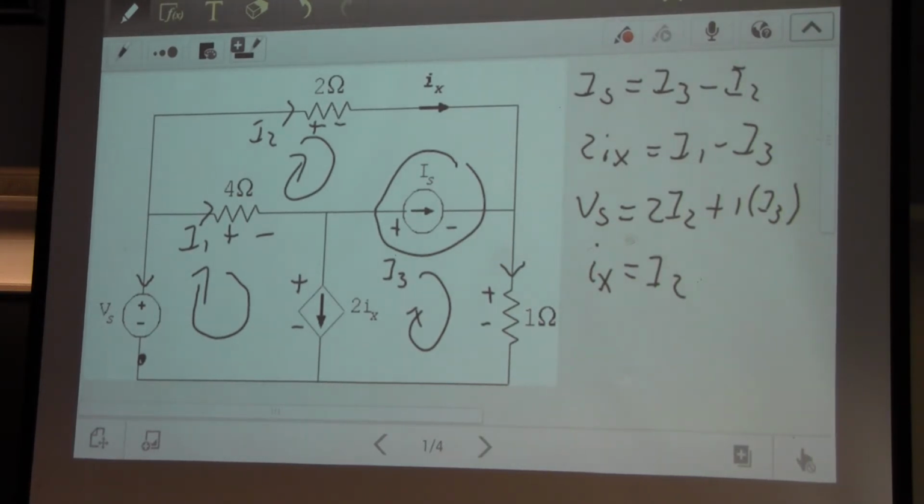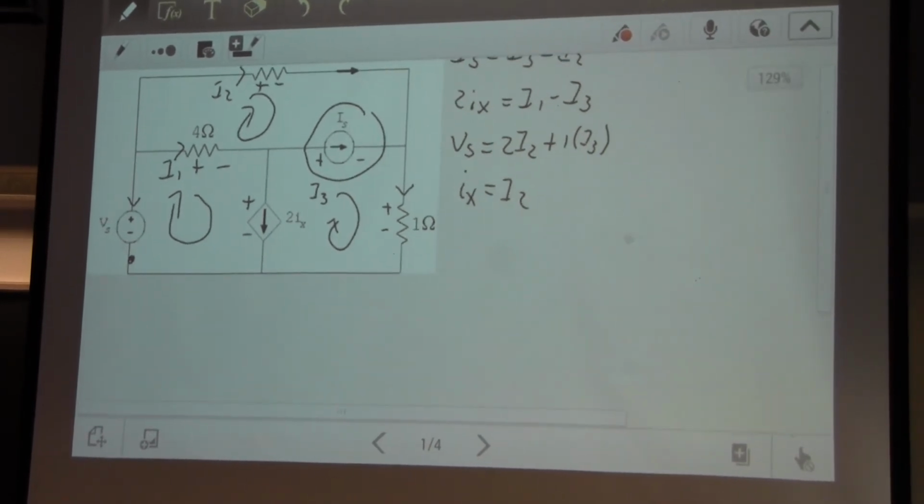Normally, what you want to do is reduce the equations and leave them in terms of the loop currents. So wherever I have an Ix, I should substitute it, which is just here. It will be easy. Once I set this up, I'm going to end up with 3 equations that look like this.